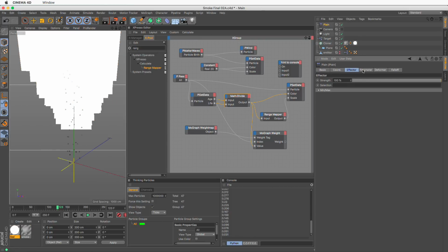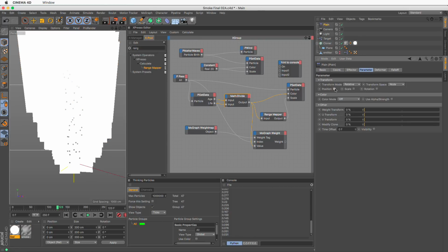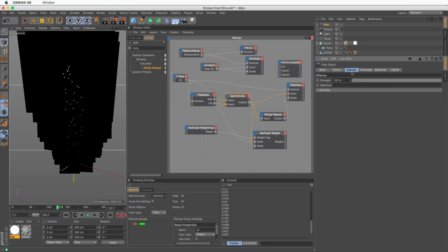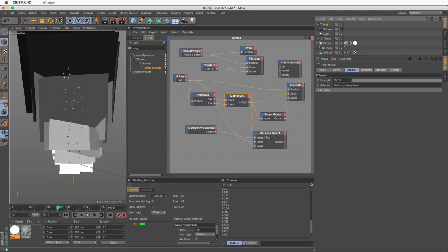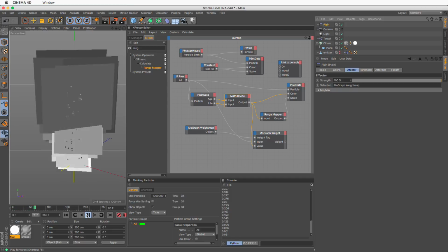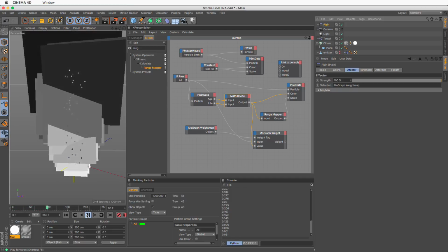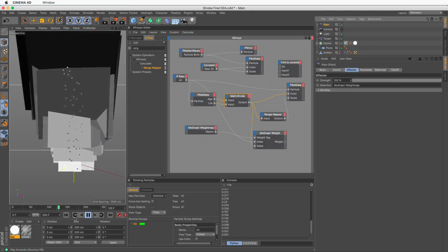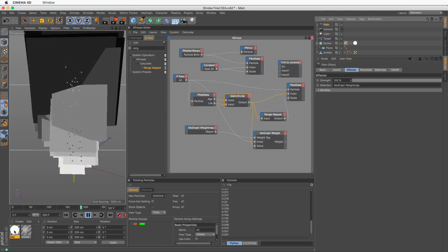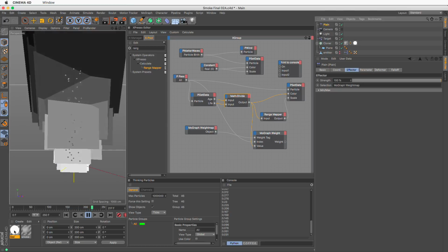I'm going to get rid of all the parameters. I'm going to set the color to user defined. Let's make it black. And now the most important part to make it work, I need to tell the plane effector to use the data from this selection. And voila! Now you can see that my placards are actually being colorized by the color shader in this material by their age, essentially, because the age is what defines what's going on.